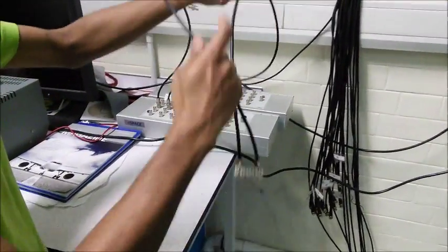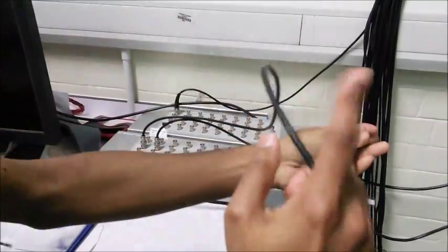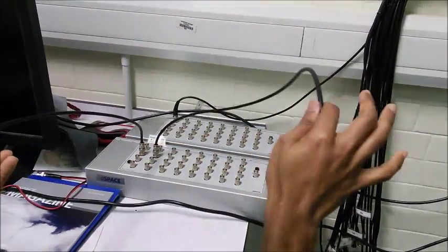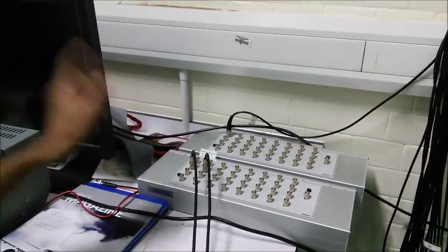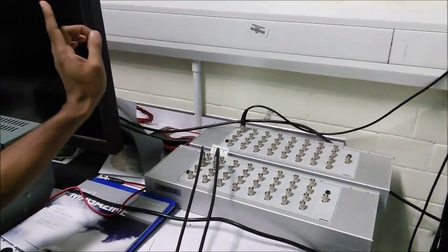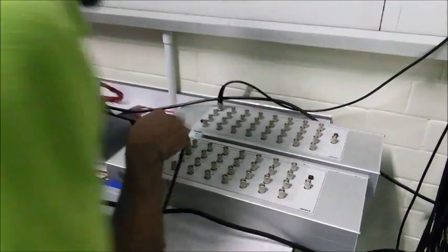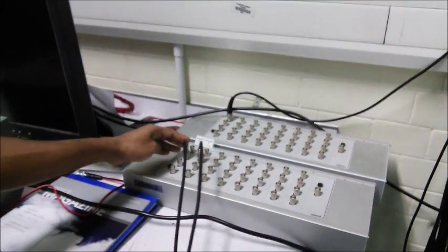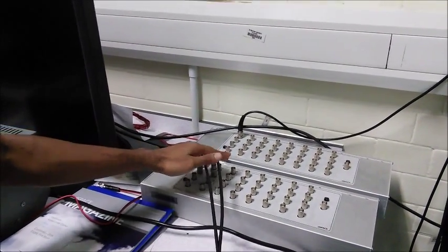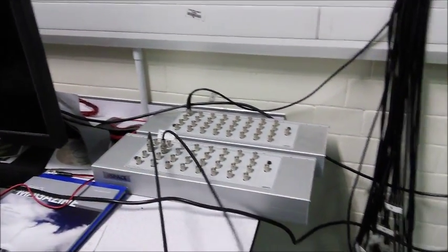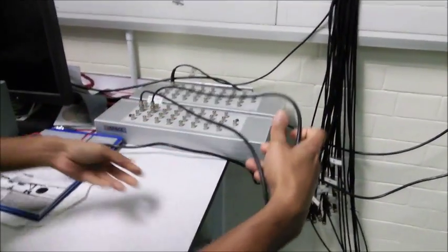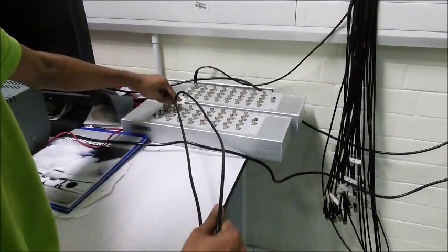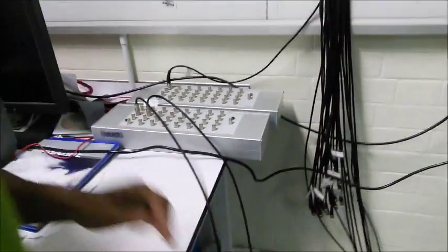So if we just figure out, what we will see is this one is for the direction and this one is for the speed. As we have assigned some channels inside the Simulink model over there, the number of those channels were channel number 9 and channel number 2. This is why these channels are already connected here in order to run the pump. So the directional one and the speed one has been connected to channel number 9 and channel number 2 in order to run the pump.